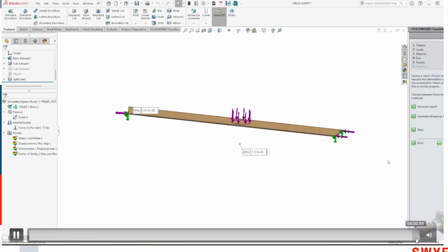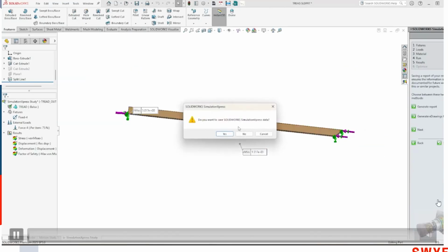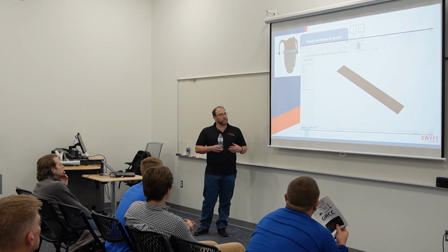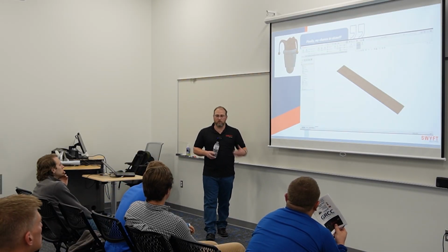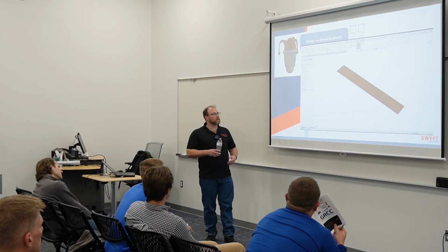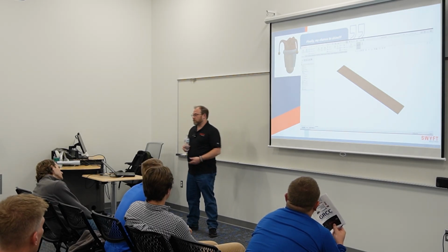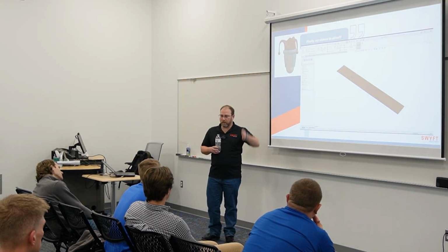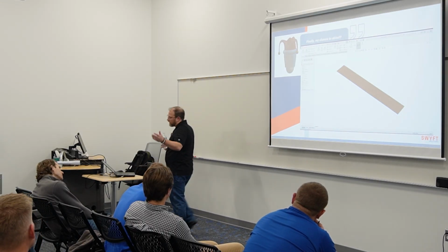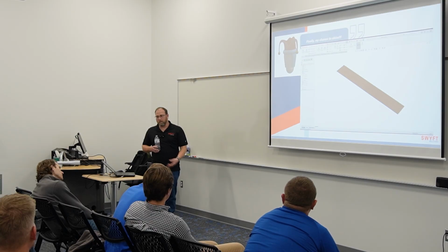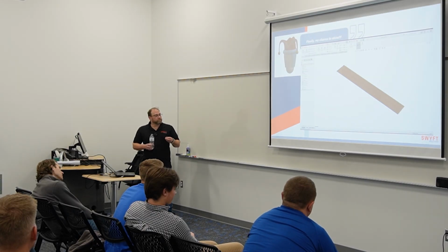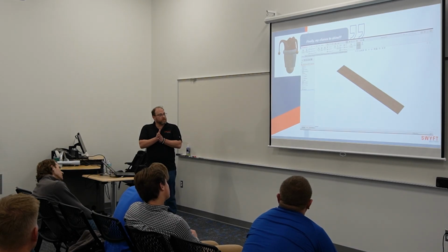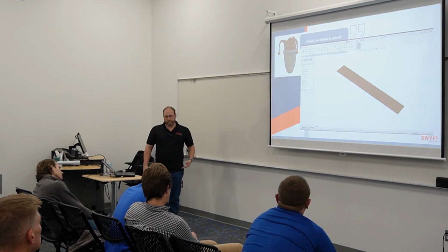Okay, so that's about all we can glean out of this for a single part. And using the split face to get more information out of it than you would have been able to with the software originally makes it so much more valuable. If you wanted to, you could put a split face on the bottom as well for where the vertical supports intersect the board. Or if you added gussets, make a split face for them. And then you start fixing those during the add fixture portion, and you get better and better results.